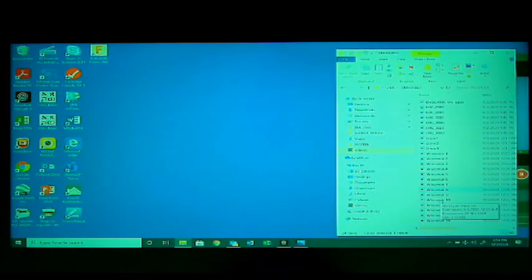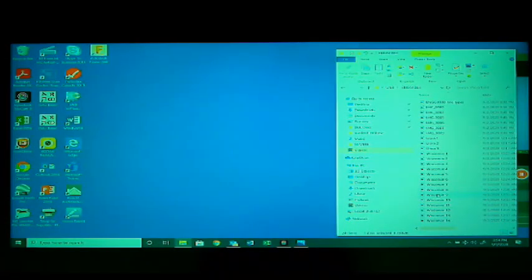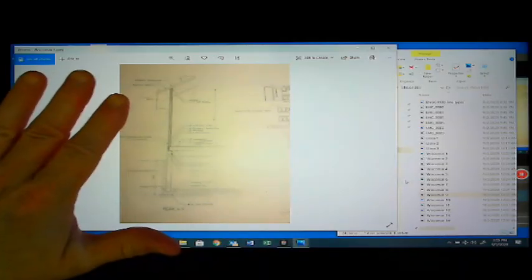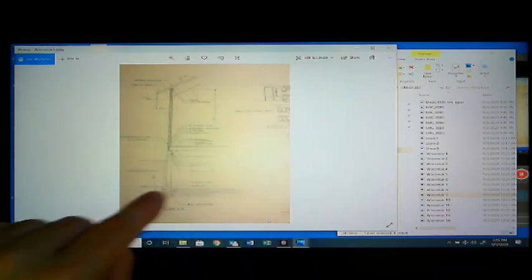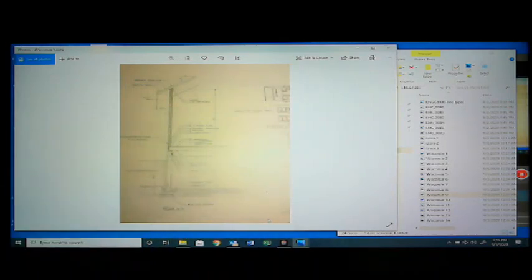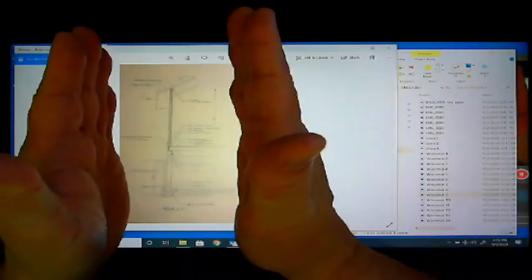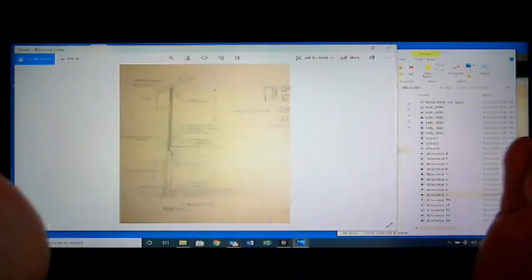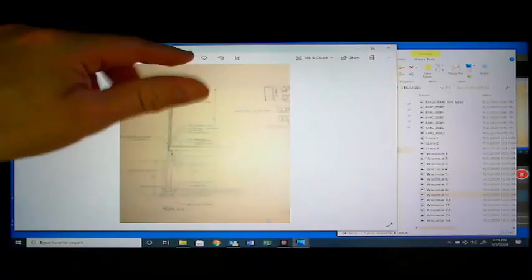So, if you look at what that was, what was that drawing? That was a section through the house cutting off the main floor so you could see the supports. Now, here's another section. So this is showing a typical wall, and you notice it says rear BB, so there would be a point on the drawing where it shows where I'm doing this cut through. And this shows a section basically through the house, about 10 feet in or so. And you can see all of the roof beams, lays out how the roof is to be done.